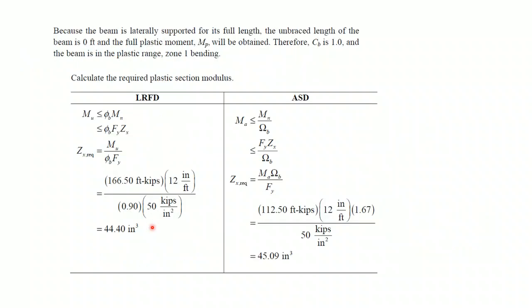Now we also check the plastic modulus of this section, which is simply M equal to Fy Zx. We know Fy, and we know Mu, which we already calculated.